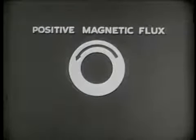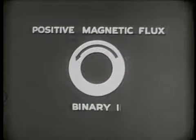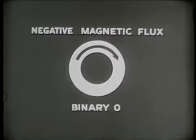Bistable, because it can be magnetized in two directions. When the magnetic lines of force point in one direction around the core, they are a positive magnetic flux, and the core is said to hold a binary 1. If the direction of magnetism is reversed, the flux becomes negative, and the core holds a binary 0.